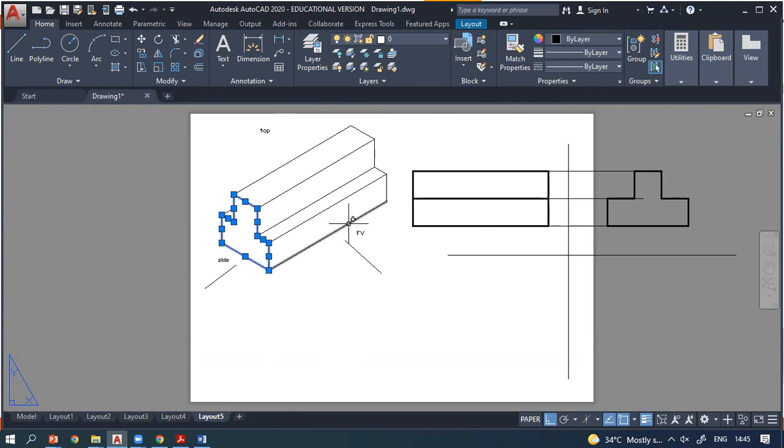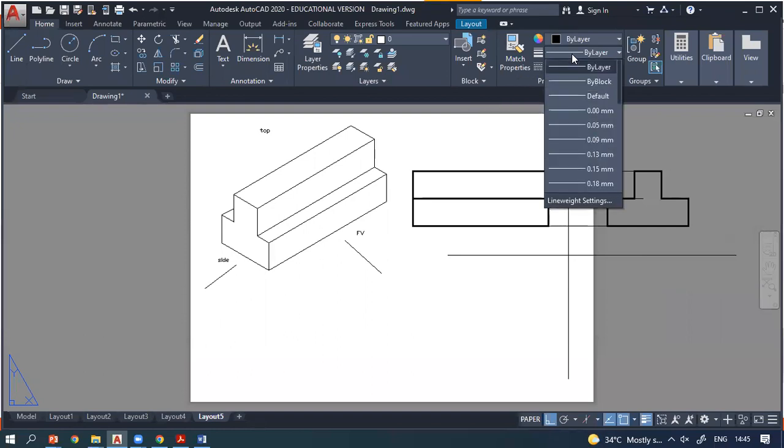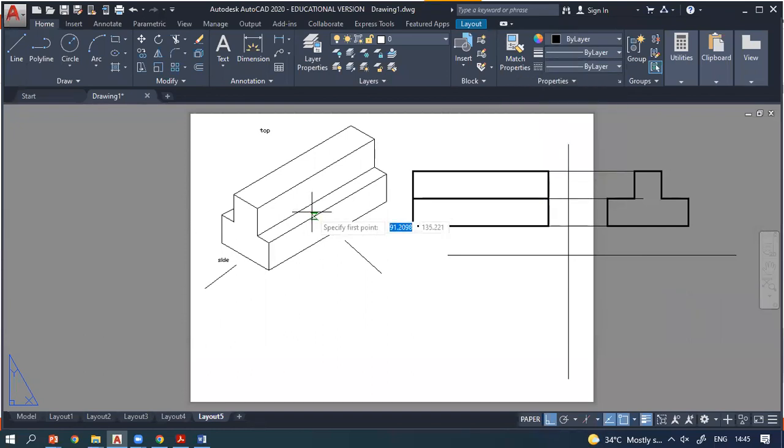What about the top view? So three rectangles. In the top view, you can see this rectangle, this one, and this, and one other one here. To get that, from here, draw a 45-degree line. Drop the perpendiculars.